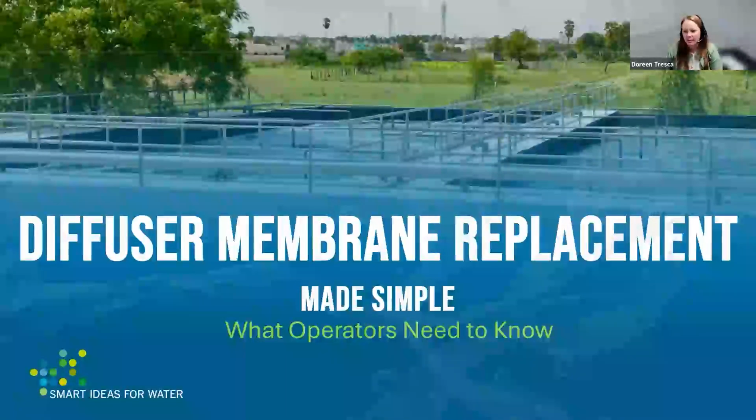Today we're going to be talking about membrane replacement, specifically what operators need to know for diffusers and how membrane conditions can impact aeration performance over time. We're going to walk through how membranes age, what that looks like in the field for operators, and how those changes affect airflow, energy use, and overall system stability.